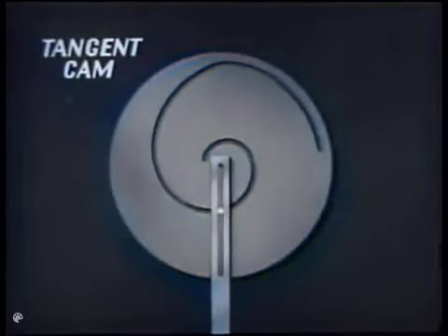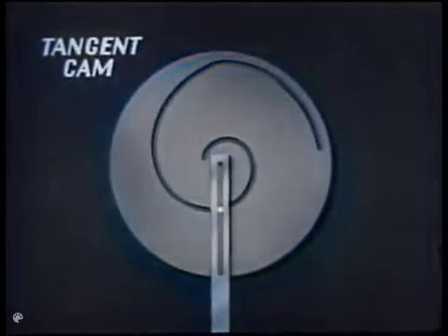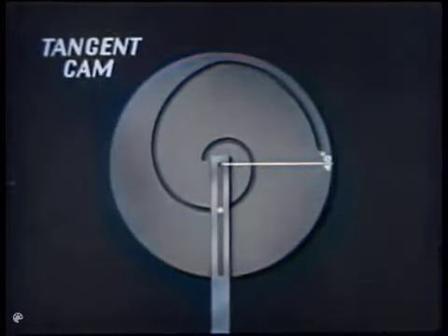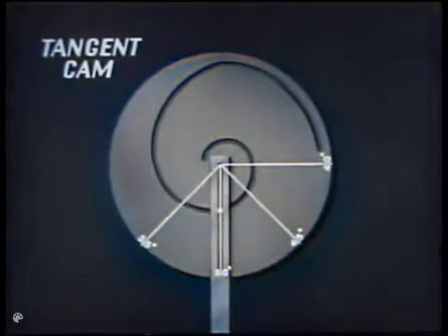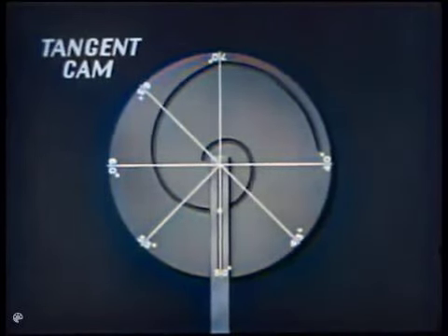The tangent cam is an example of a trigonometric cam. In this cam, the input can be any angle between 40 and 70 degrees. The output, the tangent of the angle.